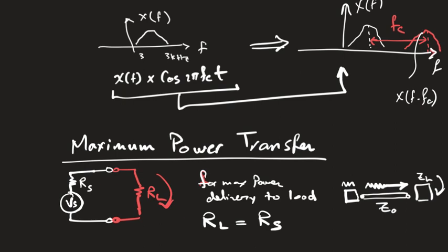And similarly, the maximum power transfer theory in the case of a transmission line says that you will achieve maximum power delivery to the load if ZL is equal to the characteristic impedance of the transmission line, okay? What if it's not? We add the capacitors or inductors. No. What will happen if it's not? I'm not saying how do you correct. Exactly. You will encounter reflected waves.